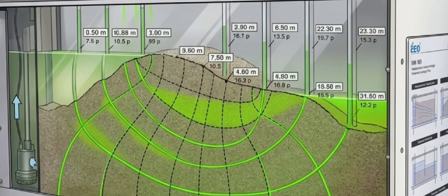In geotechnical and civil engineering, earth dams and levees are among the most critical pieces of infrastructure because they are constructed using the most unpredictable material available, natural soil. Unlike steel or concrete structures, which are manufactured to strict specifications, an earth dam must safely contain massive forces using local geology. Because a mathematical equation can never fully capture the complex, real-world behavior of water moving through soil, physical laboratory experiments using seepage tanks and hydraulic apparatuses are foundational. Here is why dam experimentation is absolutely critical to geotechnical engineering.